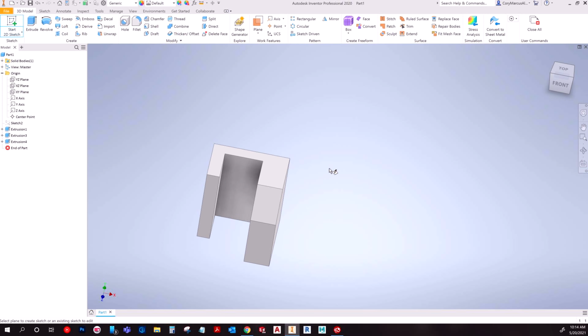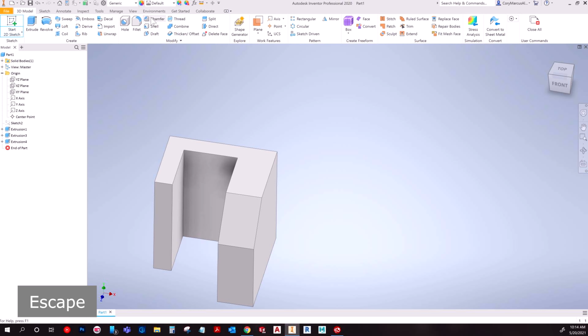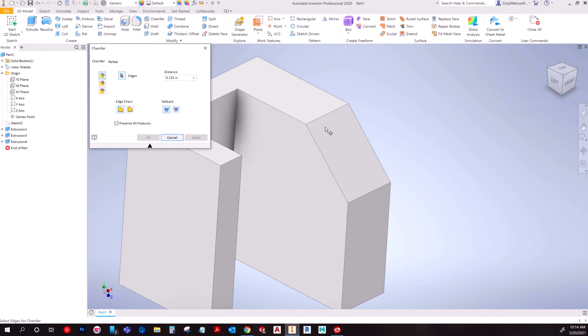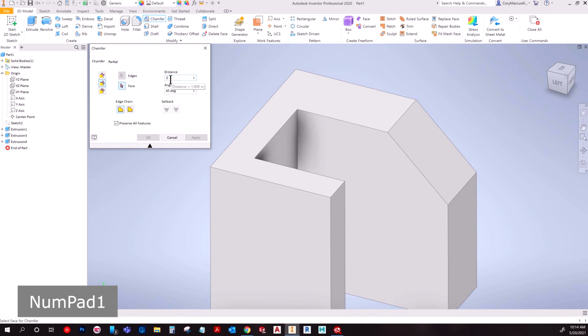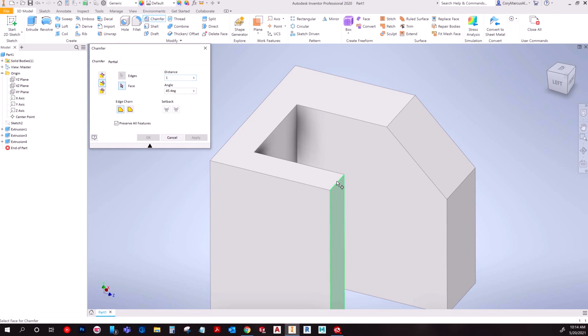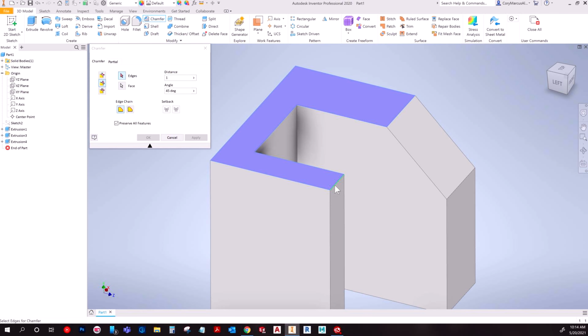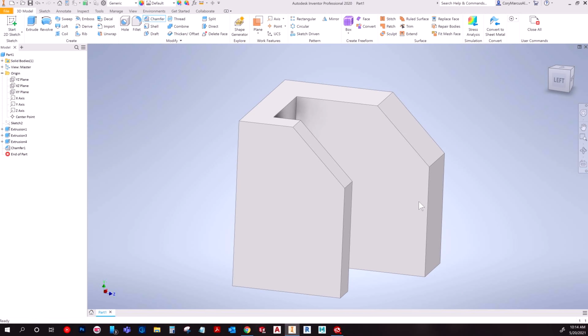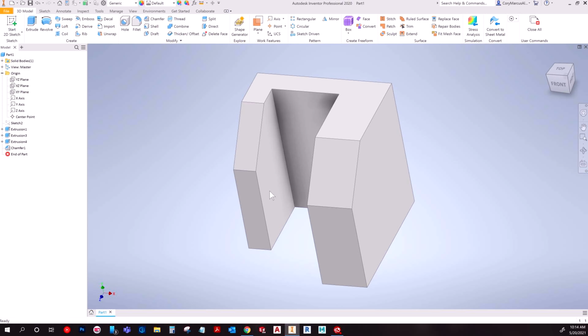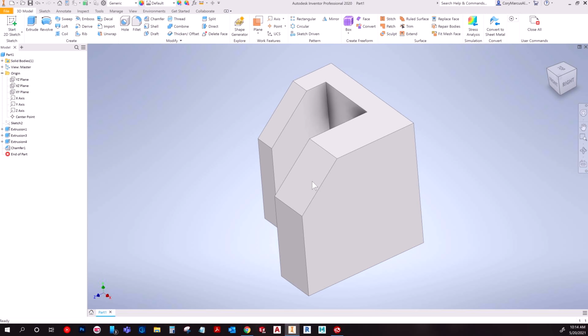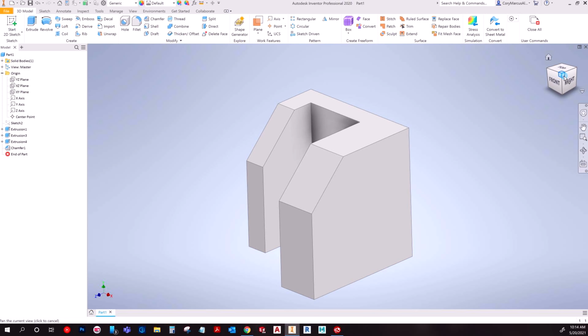And then let's see, say you did want to do a chamfer, kind of like that one there. You can actually do that pretty easy. I could do the same exact chamfer here, which is going to be that leg distance of 1 and the angle of 45, and I can click these face and edge and get that same chamfer a lot quicker. So that's actually the way that I would typically do that, but sometimes there is a cause for drawing it on a sketch level. It just depends on what you're doing.